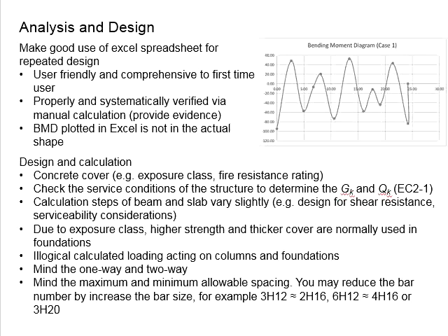As a refresher and to help you kickstart your assignment, you will need to consider the concrete cover. This can be standardized throughout all the structural elements, where you have the cover for the main structural elements like the beam, the slab, the column. They can be of one cover on the basis of the exposure class as well as the fire resistance rating.